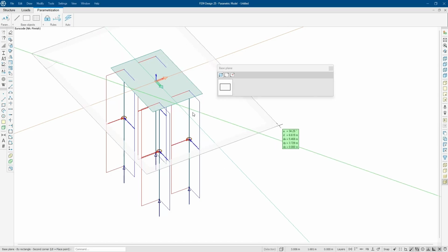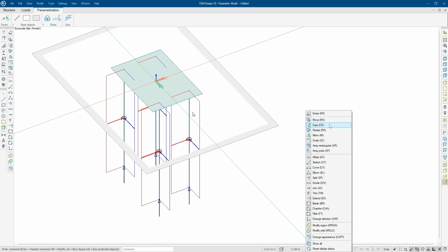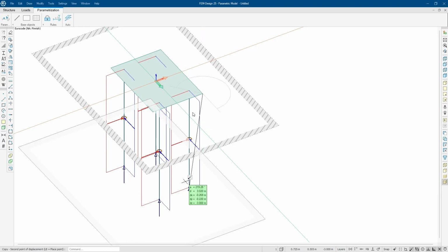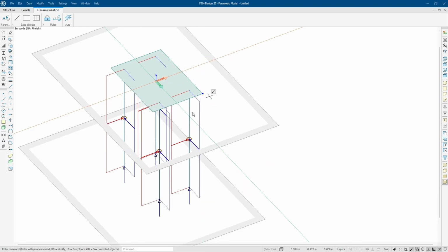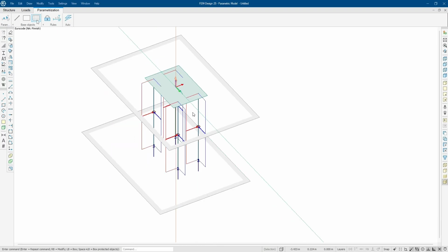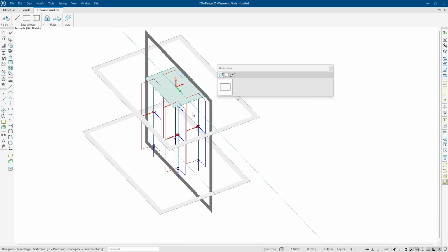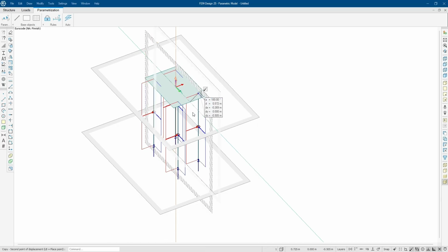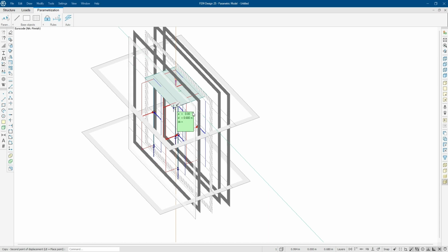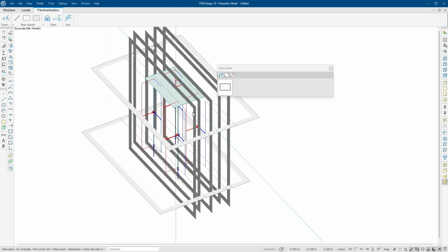And then we have to define base planes instead of base rays. So base planes are those points where we want to define coordinates. So now we have horizontal planes. And with the FEM-Design coordinate system tool, we can also draw those vertical planes. So we have to define one plane in the mid of the structure, and also in the pile endpoints and in the corners. And same applies to y direction. So we have to also define there some planes.